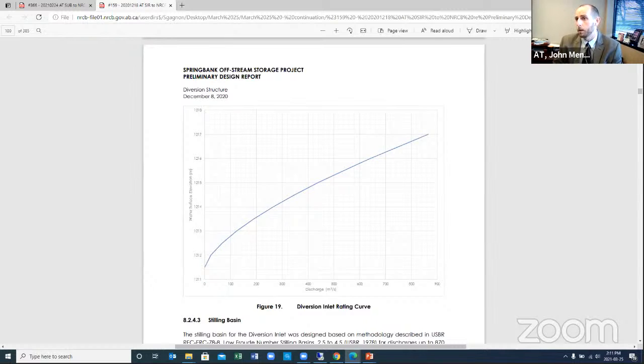What we're worried about would be water going over top of the height of our walls. And so those walls have freeboard of 1.5 meters to 2 meters. They're up to 1219. And so those are the pieces that we are focused on in terms of freeboard.